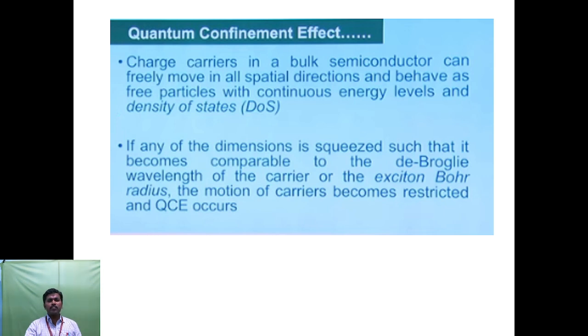The charge carriers in bulk semiconductors can freely move in all space directions and behave as free particles with continuous energy levels and energy density of states. If any of the dimensions is squashed such that it becomes comparable to the de Broglie wavelength of the carrier or the exciton Bohr radius, the motion of the carrier becomes restricted and the quantum confinement effect develops.